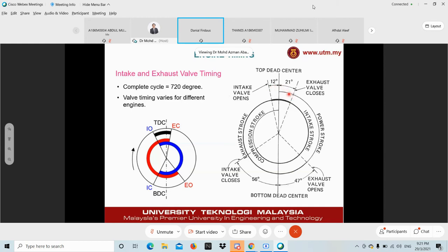Okay, because they want to delay the exhaust valve. In a normal internal combustion engine, to expel all the combusted gas, you need a lot of time for the exhaust gas to go out totally from the cylinder, which is why the exhaust valve is slightly delayed. This figure might not represent all engines, but it is just for your reference. But usually it's delayed after TDC.